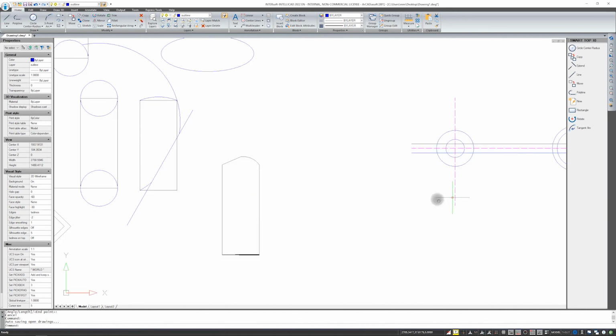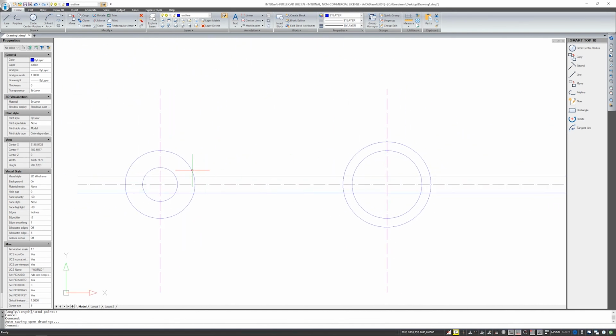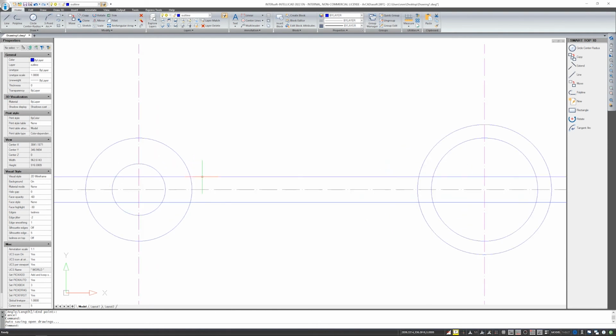We are now going to move on to the drawing. I would like these elements to be more harmonious with each other, so as to round off the connection these circles here have. For this, I need the Fillet option. Here's quite an important thing. Sometimes I select an element under the right button, select its modification, and sometimes I enable the option to modify first and then select the element.